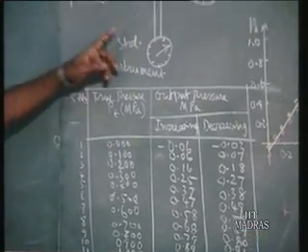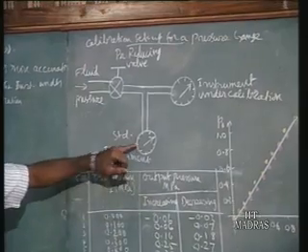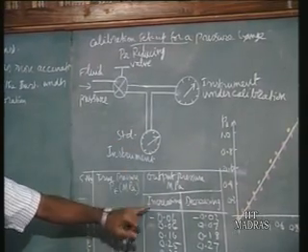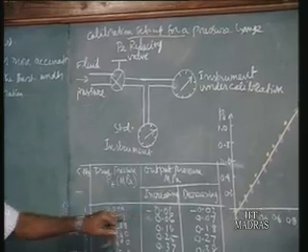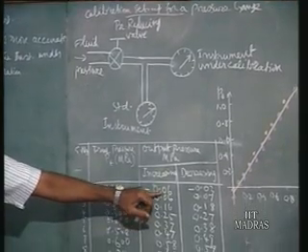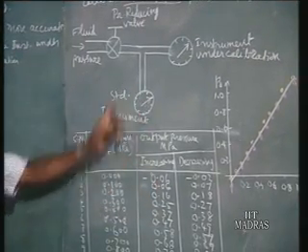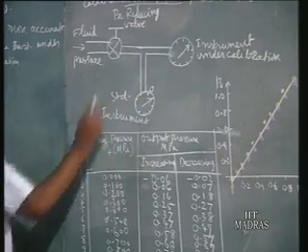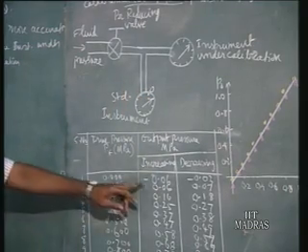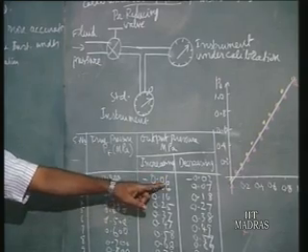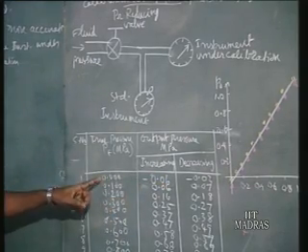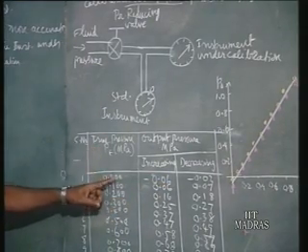Now at that time you make some measurements. You note down the reading in the standard instrument, increasing from 0 onwards. It already shows some reading, a minus reading, so below 0 there is some reading. Note it down. You find here that in the instrument under calibration we can read up to the second decimal, and that means the standard instrument should have 3 decimals.